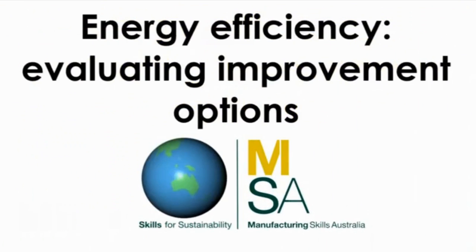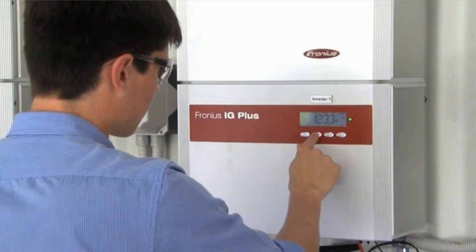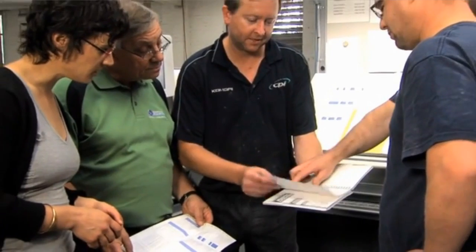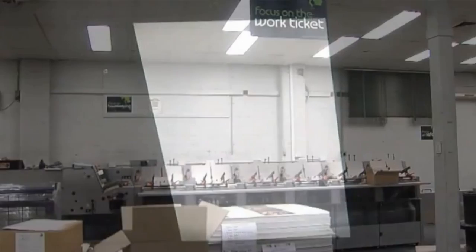In this sort of efficiency and sustainability area, cost is the major driver of either implementing or not implementing an idea. Often there are risks and indirect costs to take into account. LED lighting, which is the newest technology, very efficient but also quite expensive. Then there was a more efficient form of fluorescent lighting called T5 lighting. We ended up going with the T5 fluorescent lighting. Even though it's a little bit less efficient, even though it wouldn't save us quite as much energy, it was a more proven technology.